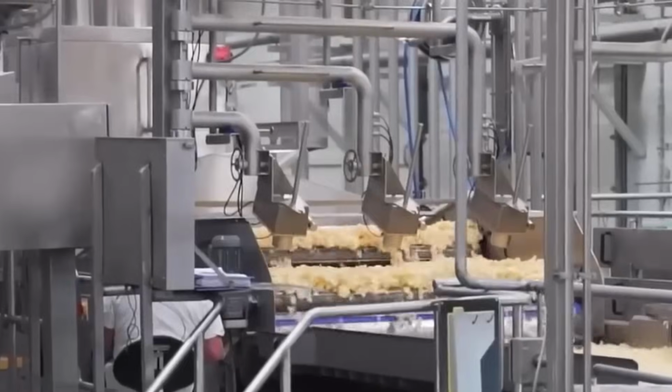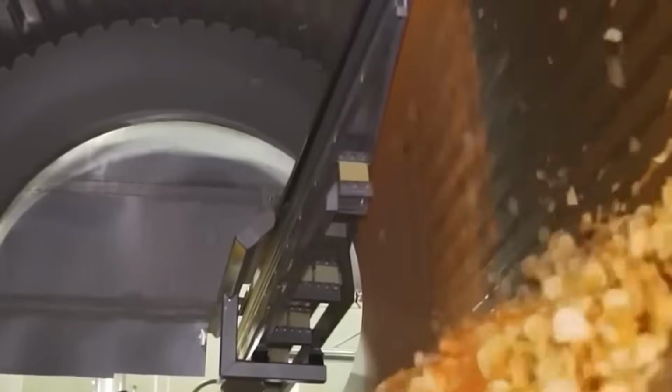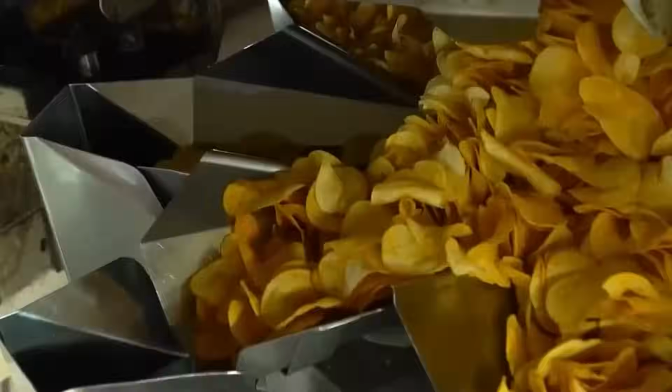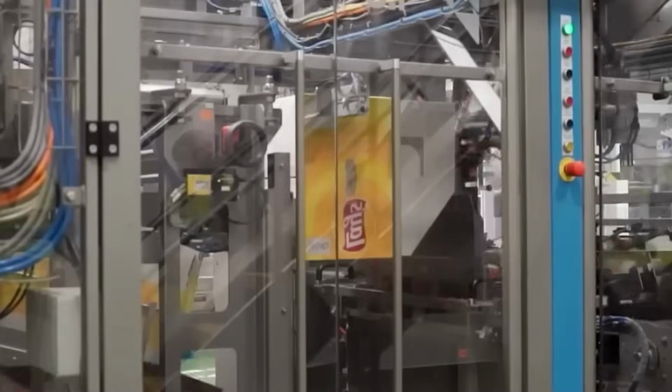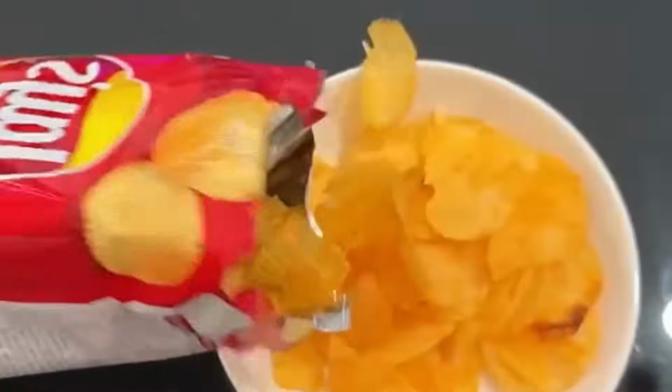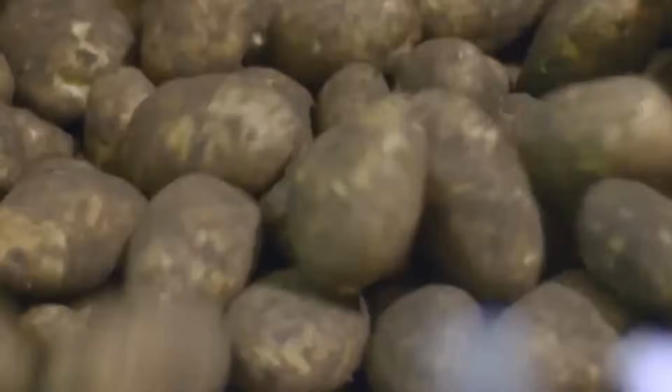Pallets are transferred to a climate-controlled warehouse held at consistent temperature and humidity to preserve texture and prevent oil oxidation. All product data, including ingredient lot numbers, frying oil batch, line performance data, and packaging codes are stored in the plant's MES database for full traceability. Throughout the process, ingredient inputs, machine speeds, temperatures, moisture levels, oil quality, and product weights are monitored in real time by integrated control systems. Operators interface with the process through HMI panels, which display alarms, trends, and machine statuses.